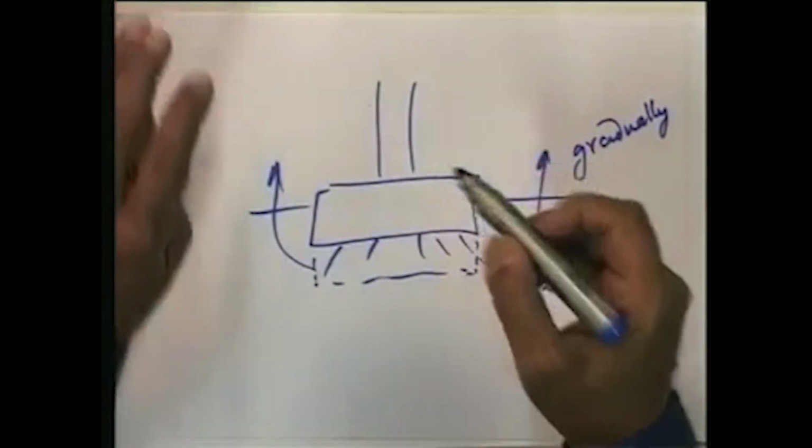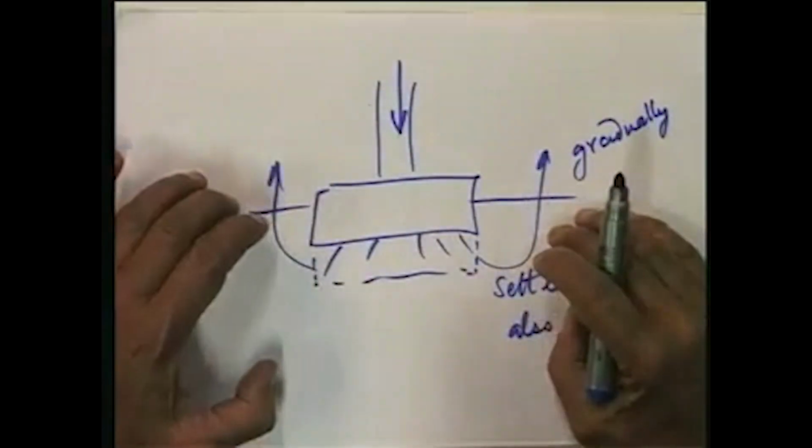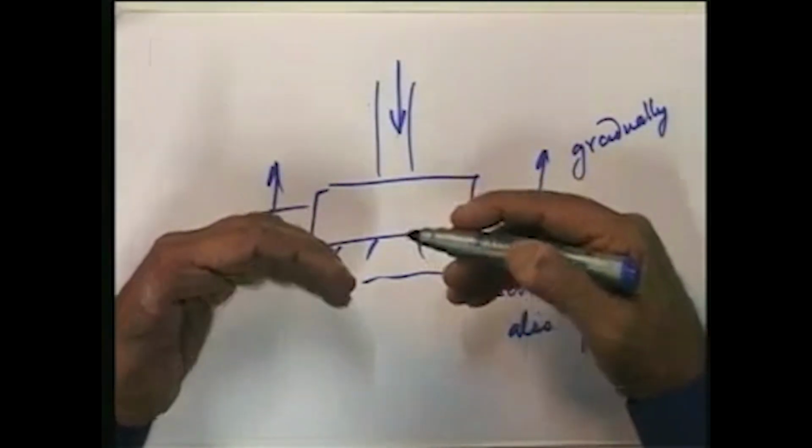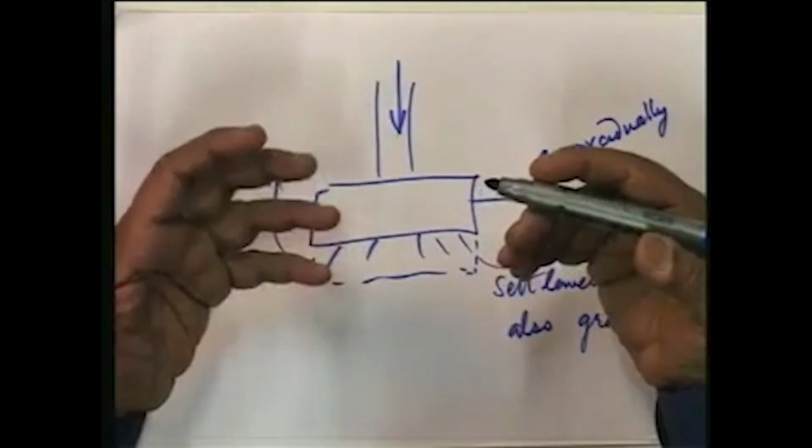This means that under certain load, under certain soil conditions, the settlement is going to take place as a function of time. Now, the question arises, will it take place indefinitely? How long will this settlement take place? Well, practice or experience shows that this settlement will go on taking place theoretically up to infinite time, but in practice it stabilizes after a certain amount of time, and that is the total or the final settlement corresponding to a given load, a given structure and a given soil condition. And it is possible to calculate that total settlement, that is one type of computation.